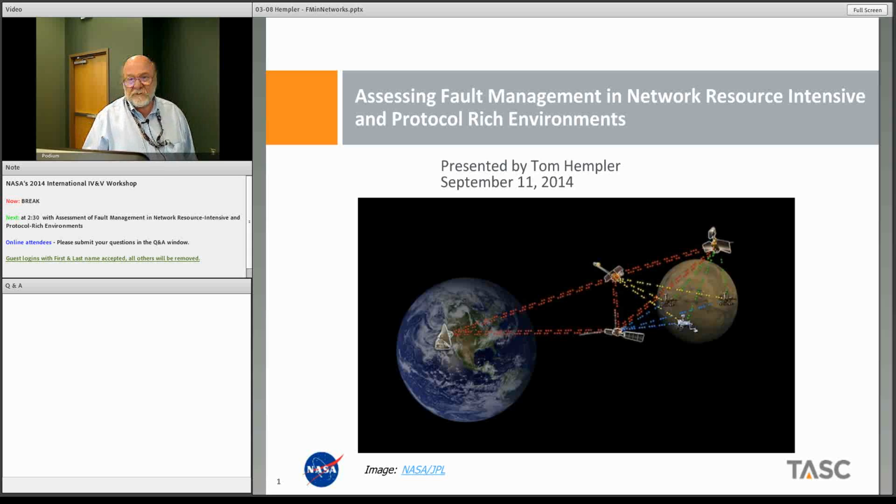It runs on internet. It's a network that runs on standard internet protocol. There are a lot of other protocols that are encapsulated by the internet protocol it uses. So what we're concerned about is the fault management concept for it. Now, normally on spacecraft systems in the past, we've done fault management, but relative to internal faults to the spacecraft. And so it's usually some lookup table on board the spacecraft that handles or manages the faults.